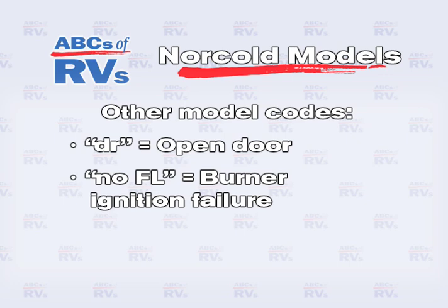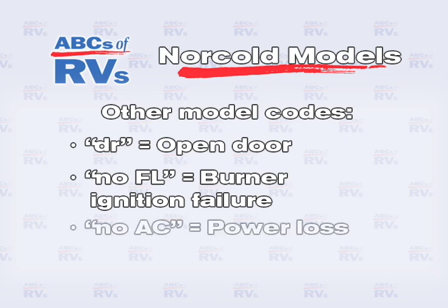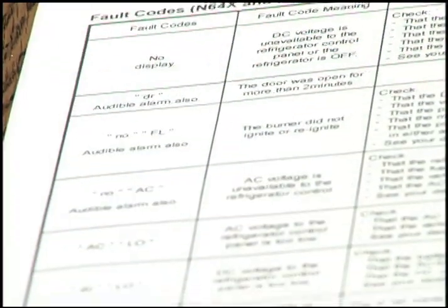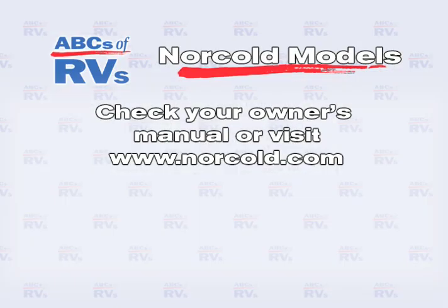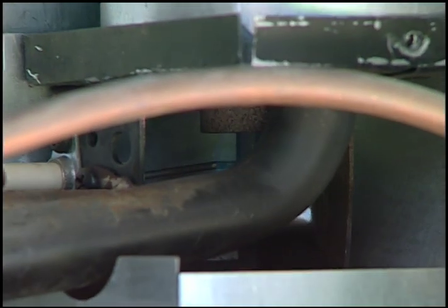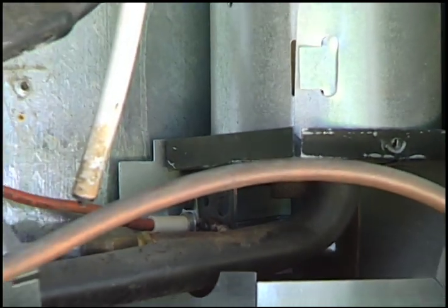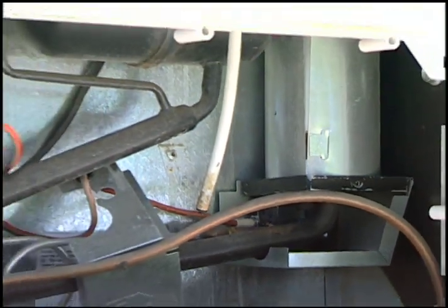No FL indicates a burner ignition failure. No AC for power loss, and more. Check your owner's manual for fault codes specific to your model or visit www.norcold.com. The efficiency of your refrigerator while operating in the gas mode is dependent upon the correct burner flame.